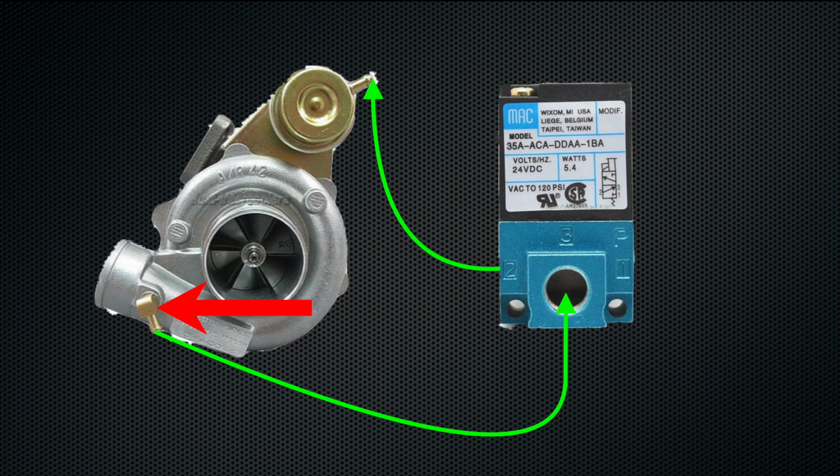And if the wastegate actuator is rated at 10 pounds and we're giving it a boost reference, it will open up that wastegate actuator and regulate us to 10 pounds of compressed manifold pressure. So even though the exhaust pressure isn't directly connected to the manifold pressure, the boost pressure that we can measure coming into the intake manifold, the wastegate actuator does a pretty good job of regulating to wherever we want to be at. In that situation, if we just simply remove the line that's going to the wastegate nipple, it'll allow us to build maximum boost pressure.